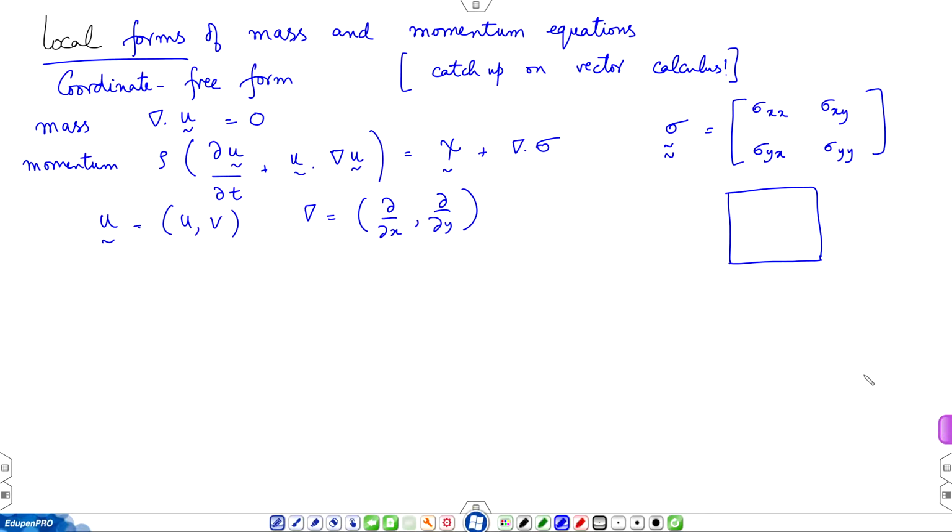So, in the form of a schematic, this is sigma x x, which is the force acting on the x face. X face is the face to which x axis is normal, and the second subscript is the direction of the force itself. So, x x. This is sigma acting on the x face in the y direction. So, in this manner you can make other entries. This is sigma y y. This is sigma on the y face in the x direction. So, on the right face, the stresses are shown in the positive direction just by convention. So, you can fill up the rest.